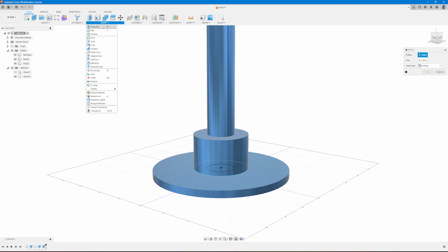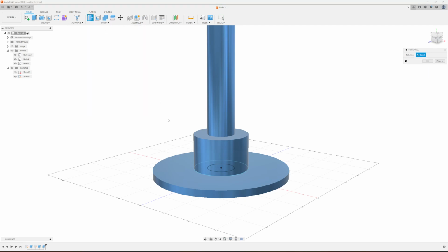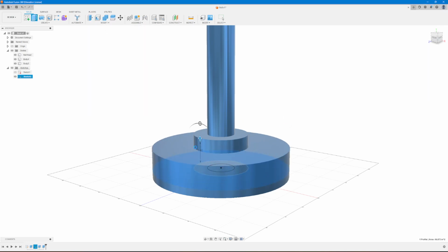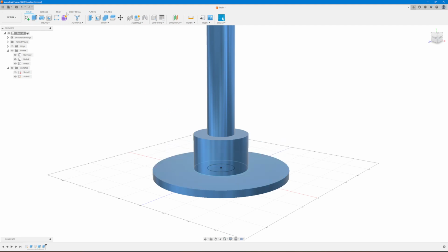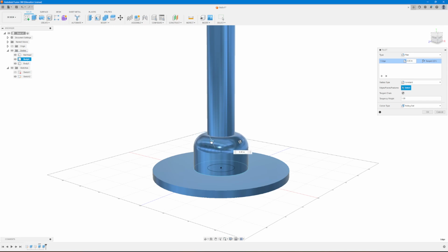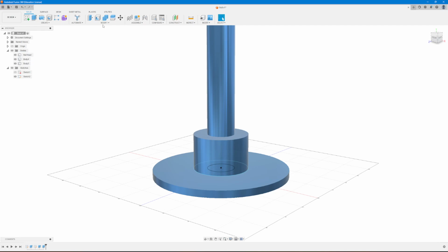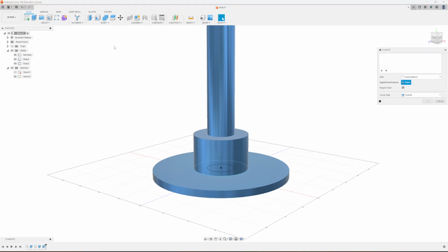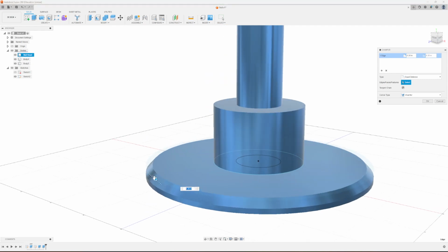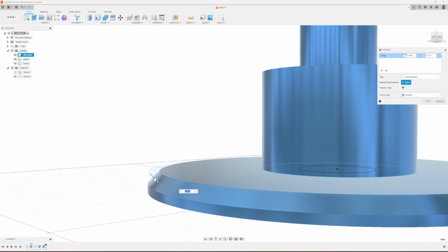So let's just go ahead and deal with the top 3. So press and pull is very similar to extrude, right? So I'm going to cancel that. We don't want to do that. Fillet. So if I click on a corner, this will round the edge. This is pretty cool. And then chamfer. Also, this will not round the edge. It will give it a nice bevel. I believe that's what's called a bevel.